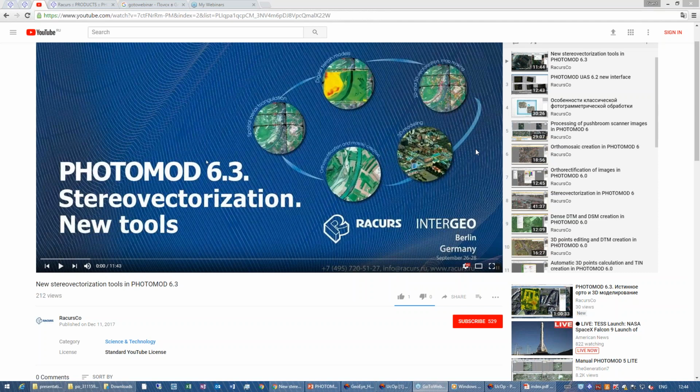To use this low block quality option, you need to import projection centers and you need to split your block into strips. It's obligatory conditions. This situation very often occurs when rotation angles are not good enough.